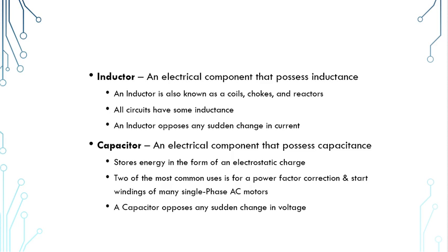Single-phase here in the continental United States would be 120 volts nominal and 240 volts nominal. Now, because they work off of magnetic inductance to get these motors to start and run, it's hard to get them to start because their poles, depending on where they are in rotation when they shut down, we might not have a very good magnetic pull to get them turning. So we'll use those capacitors to give us that 90 degrees phase shift to help get it started in its rotation. Sometimes we use it to keep them running.